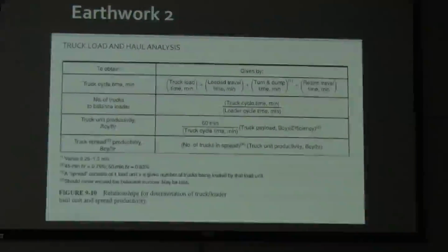Number of trucks to balance the loader. We have to have trucks waiting to pull up when the first truck leaves. The next truck has to pull in so that it can fill it. So if we're traveling a long distance to unload it, the turn and dump time, then we're going to need more trucks to keep our balance so that the loader isn't sitting idle and we don't have too many trucks sitting idle.